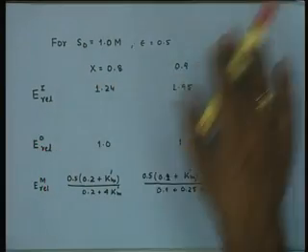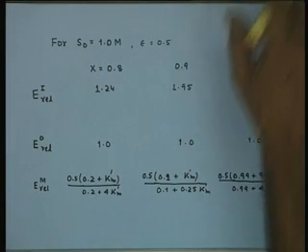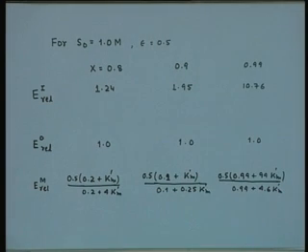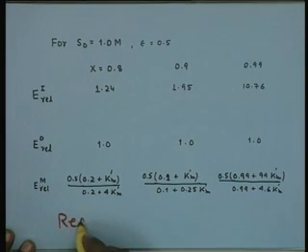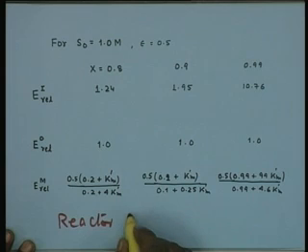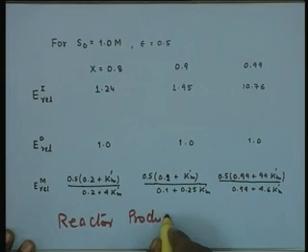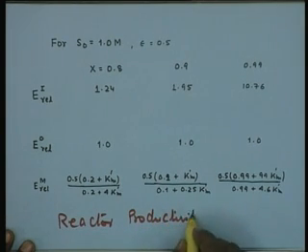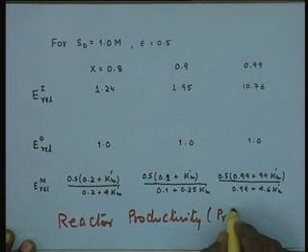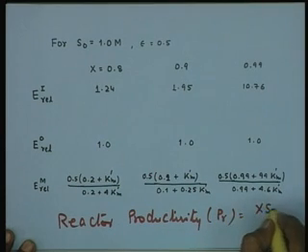So, this is the point. As a matter of fact, there is another point besides the fractional conversion, the enzyme quantity required and the space time required. There is another important parameter of reactor design, which you will recall when we defined the parameters: productivity, the reactor productivity. That is your PR, and we defined it as x S0 upon tau.